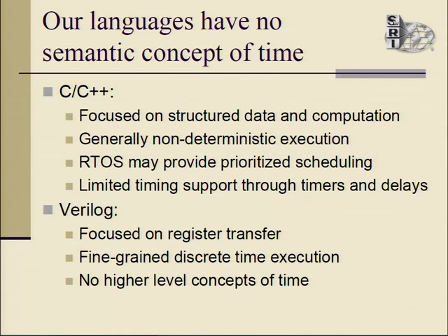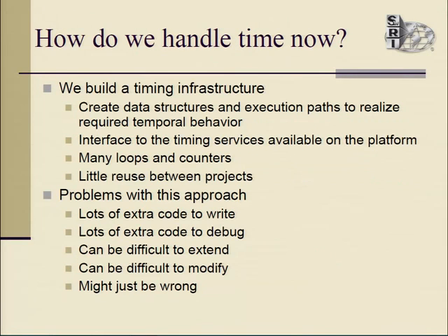Verilog is a little better. Verilog is, of course, an example of a language you would use to develop firmware for like an FPGA. But Verilog is focused on register transfer, again, computation, updating registers. You do have more deterministic execution, but the timing granularity is very, very tight, maybe nanosecond timing, and any sort of higher level timing concept is just absent from the language.